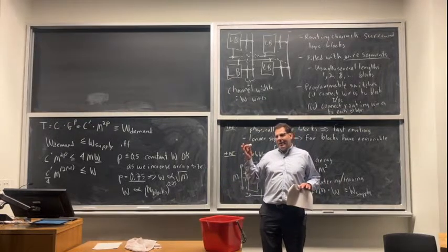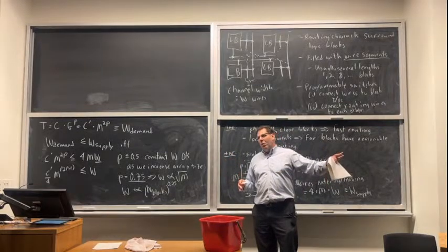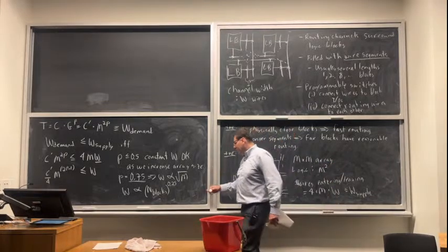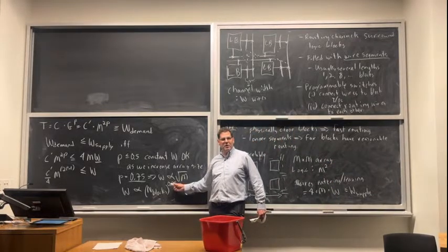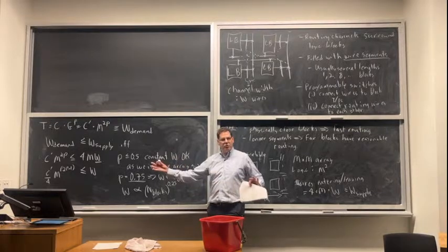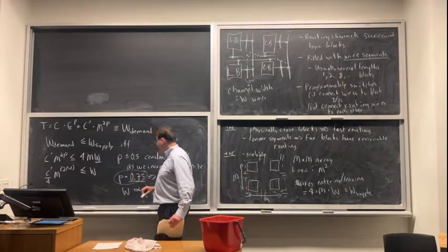If I had something that is, let's see if I can do this properly. So say I have one device that has 1 million lookup tables and another that's 16 million lookup tables. The one with 16 million lookup tables would need routing channels that are twice as wide, which is not trivial, but it's not terrible for that huge density range. In practice, this is pretty poor locality.